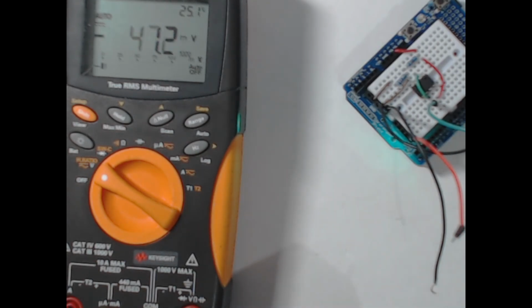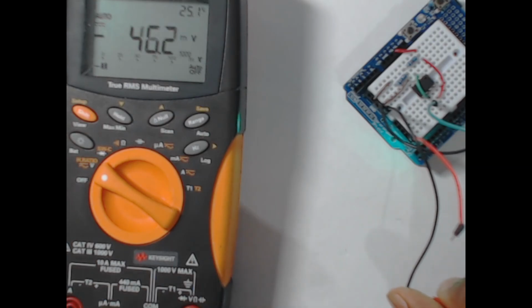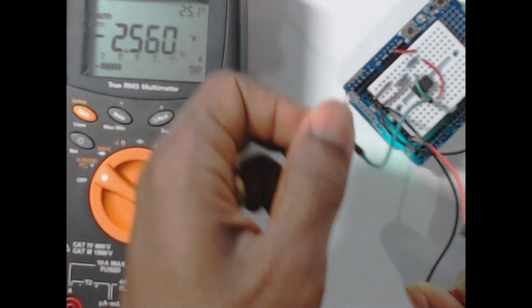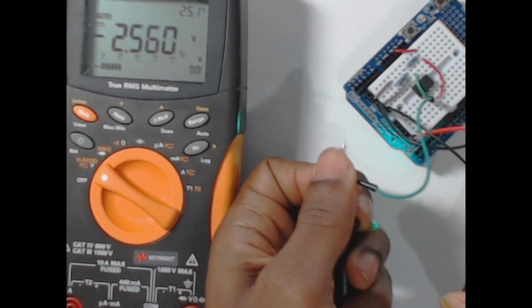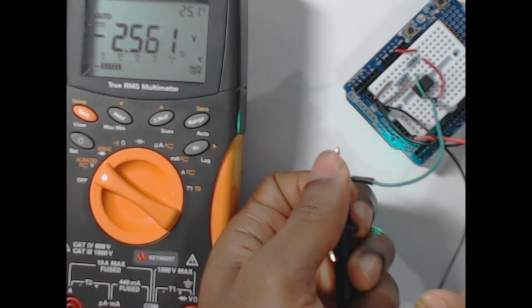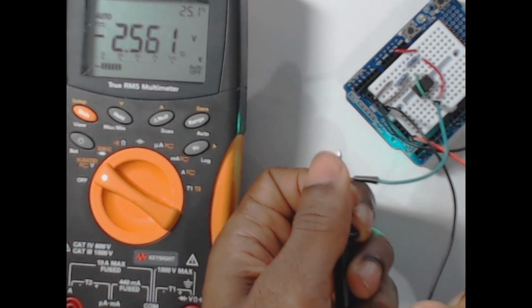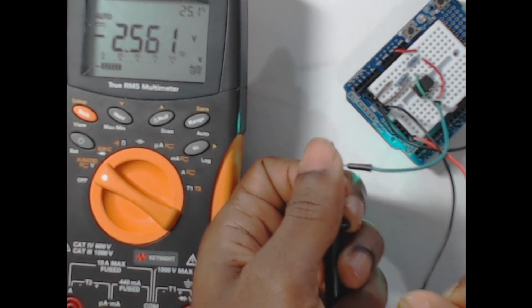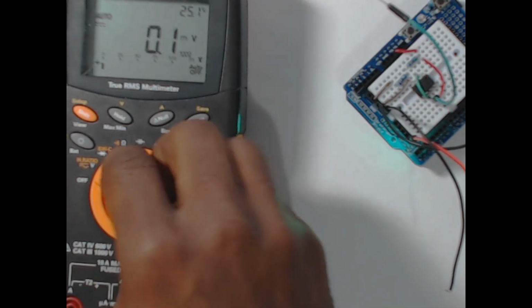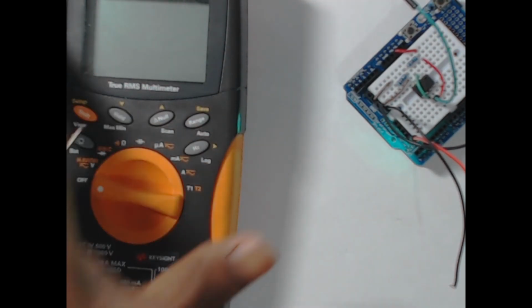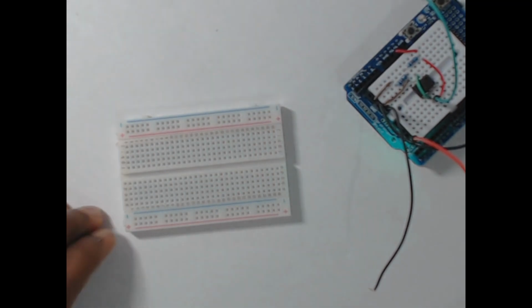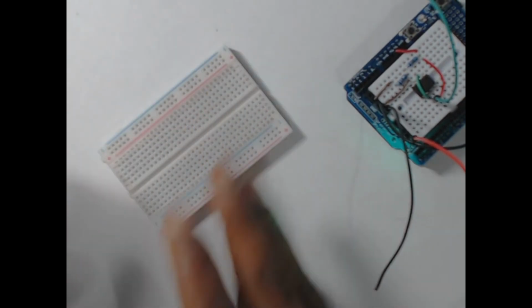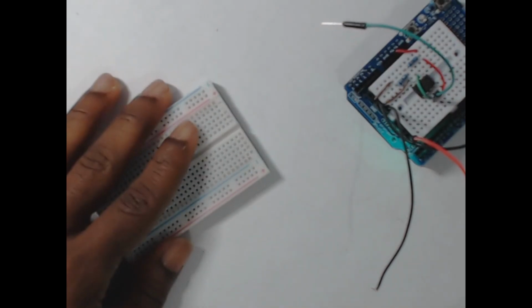You put your negative on the ground terminal, and you put your positive on the virtual ground. Put your positive on the ground terminal and your negative to the virtual ground. That's 2.56 and 2.56. We'll take that. So I wish you all the best. It means now that you can connect this to other breadboard circuits, other differential amplifiers, inverting amplifiers, or any other circuit you want to make. Thank you.